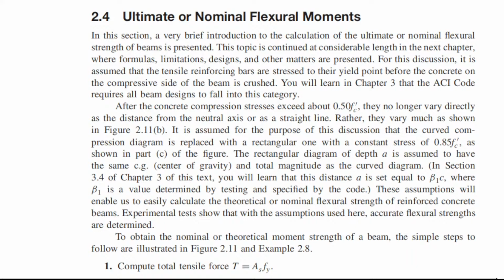So for this current explanation, let us assume that tensile reinforcing bars are stressed to their yield point before the concrete on the compressive side. Listen to that very important statement. Tensile reinforcing bars are stressed to their yield point before the concrete on the compressive side of the beam is crushed.